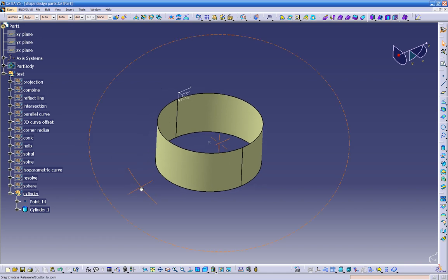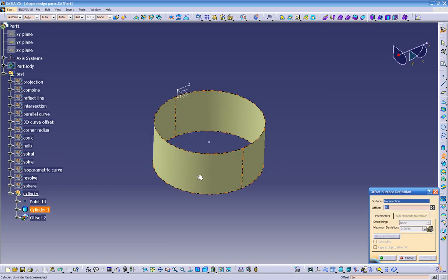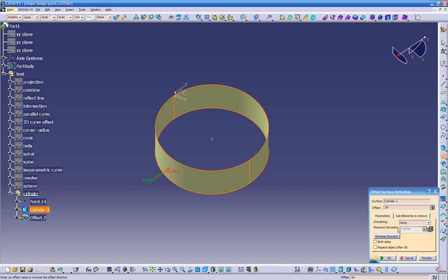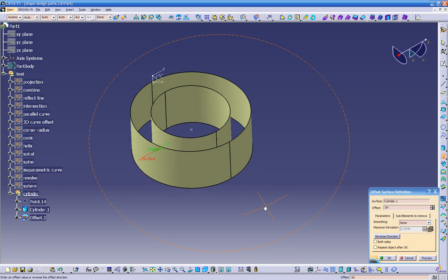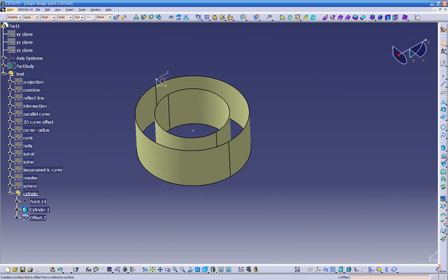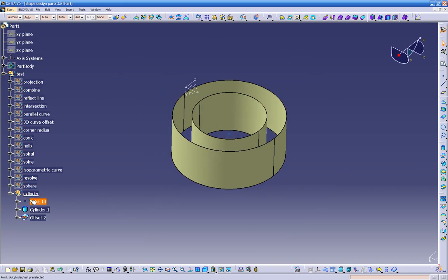Let's go to our next option. It's offset. Just click on any surface you want to offset, give it a dimension, and click preview or reverse. That's pretty self-explanatory. Same thing with this. Rough offset works the same as this, and variable offsets works the same as this, but you can change the offsets. For example, if you have a pad over here to 1 inch and you offset this 2 inch, you can do it in the variable offset. Let's see if we can make a quick sample.